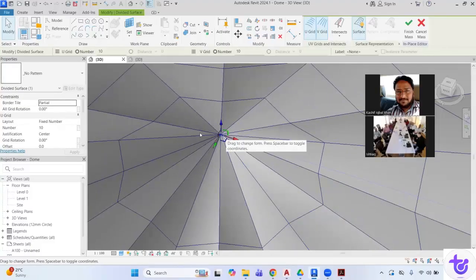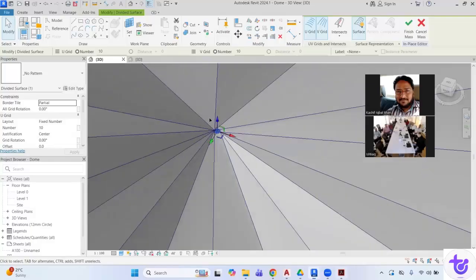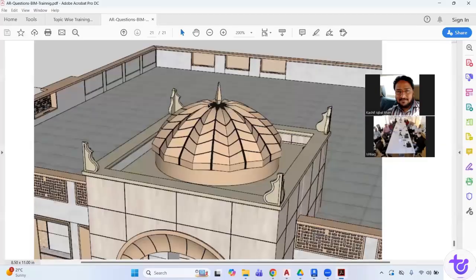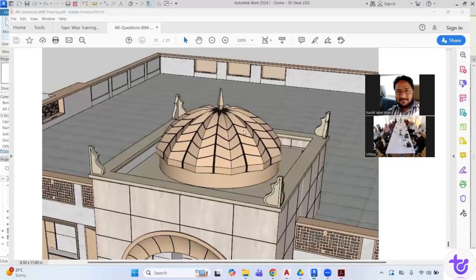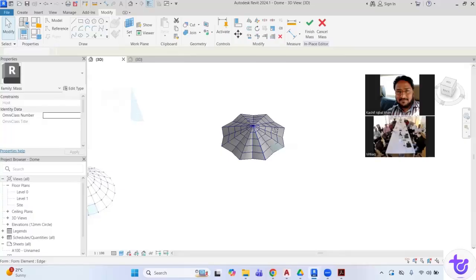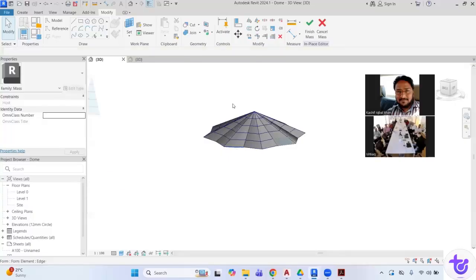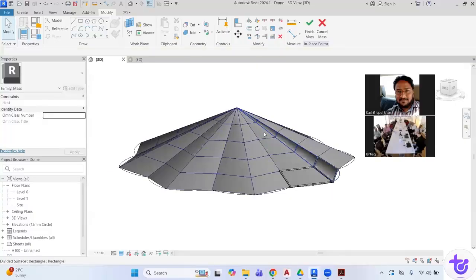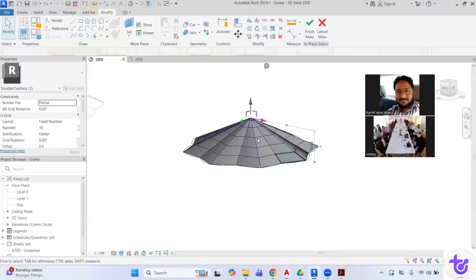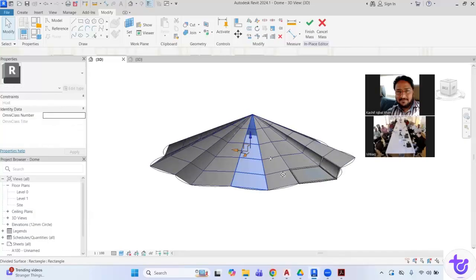Because I don't create such geometry at the top, just selecting both of them, the bottom one and the top one, making a form, just the same as we create the blend in extrusion and other things. So the bottom profile we have, the top profile we have, we can just merge them to have a dome like this. Once it is done, we have different faces.